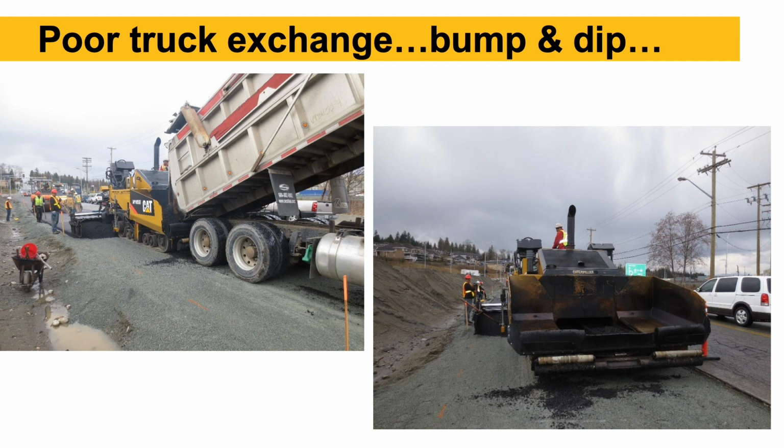Another common mistake that I see on paving jobs is, if you look closely at this picture on the left side, if you look back at the screed, you can see mix back there. They're paving along. That truck is now lowering the truck bed, getting ready to leave the paver. And then on the right side picture, you see the paver ran that hopper empty. But if you look back at the screed, you still see mix back there. And I see this a lot.